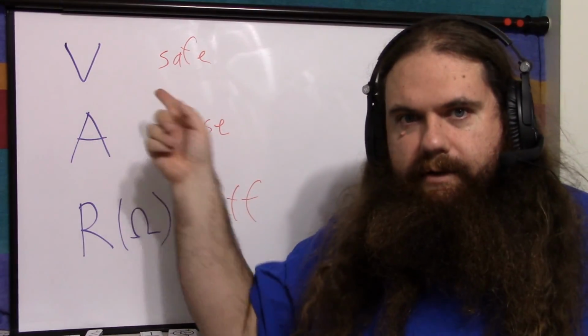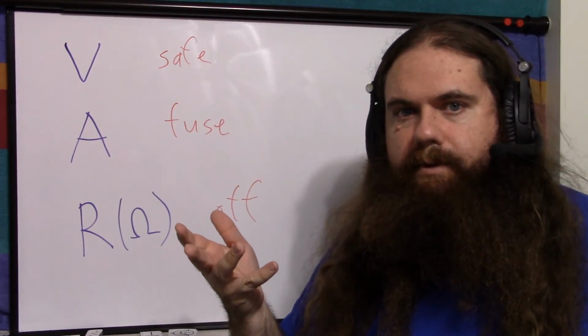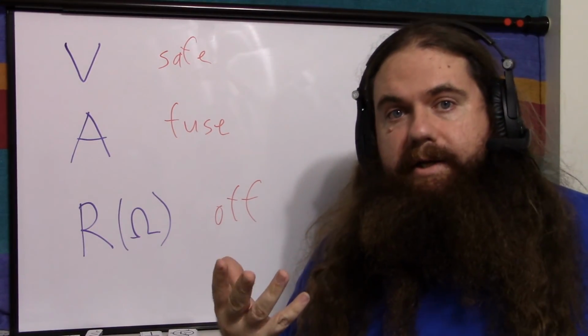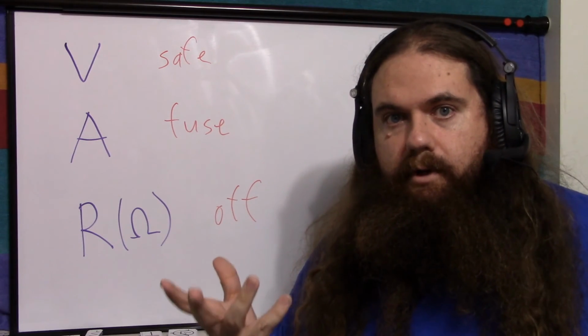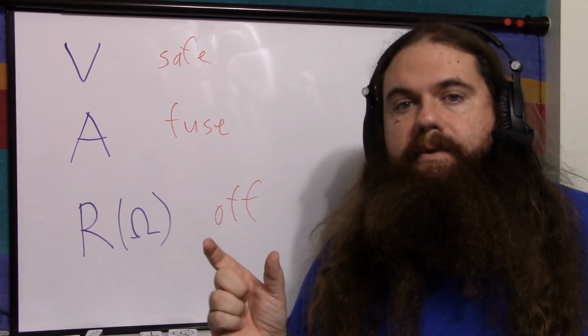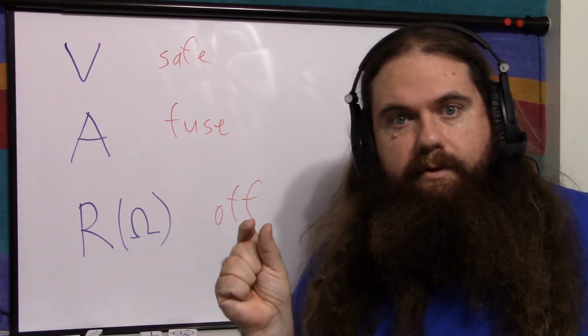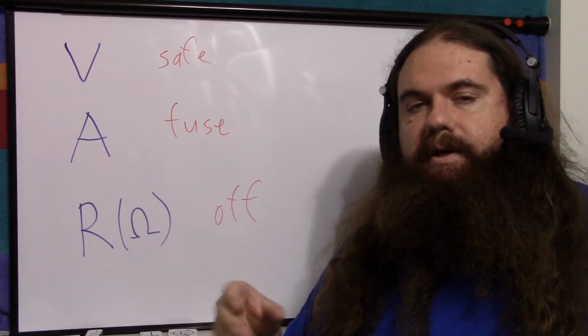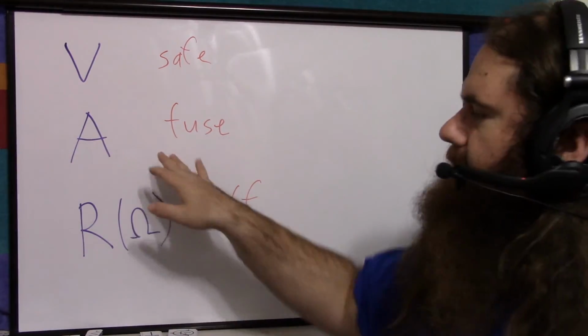So if I want to analyze the speaker port of my computer, I can plug a voltmeter right into that speaker port. And I might get no measurable signal if that high impedance ends up being a problem, and then I can turn the impedance down and use other methods. But as a first thing, just to see what happens, it's safe, because at worst, you get a trickle. The amp meter